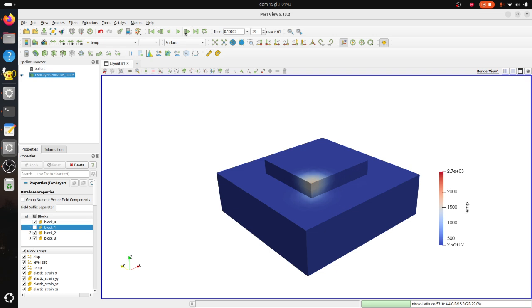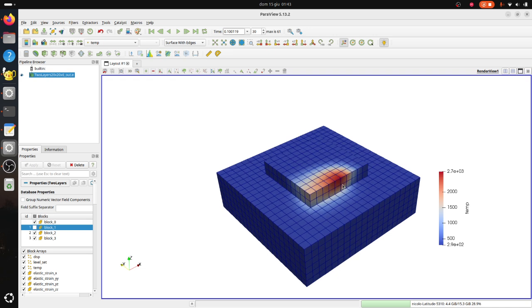you typically need to choose a time step. So between this situation and this situation, the solver has taken 1000 time steps, which is quite a lot. It means that if you want to integrate this problem properly, it takes maybe 100 time steps per element. And this is very important.